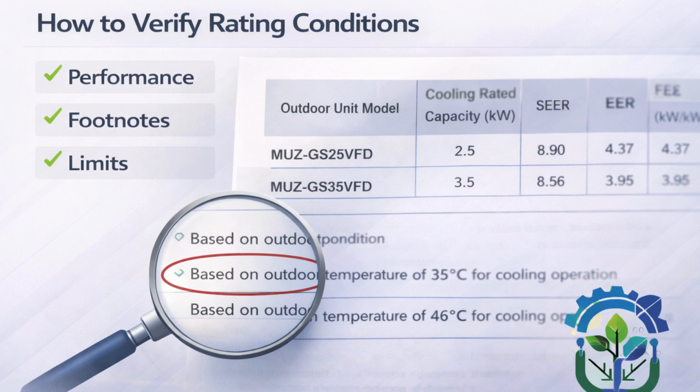So what would a T3 unit show? When correct T3 compliant data sheets are submitted to you, they will show cooling capacity declared at 46 degrees Celsius. For example, a rated capacity of 1.5 ton at 46 degrees Celsius will be clearly mentioned in the catalog or data sheets. Power input is clearly stated.